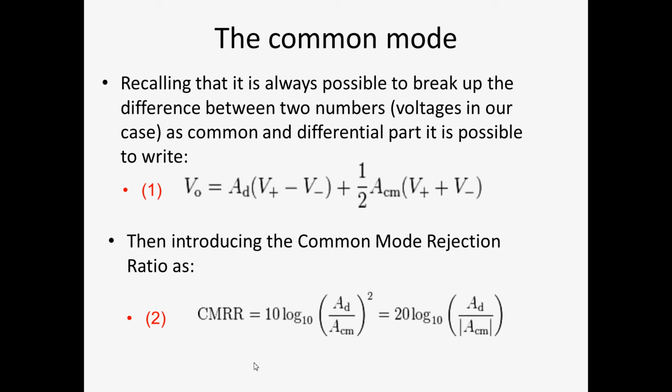Why? Because that evoked potential is so small, a fraction of a microvolt, that it is really at the boundary of the noise of the amplifier. Common mode noise, biasing, imperfection, and all these kinds of things. The only way that you can show that that thing is real is if you see it multiple times. That's why you do the averaging.